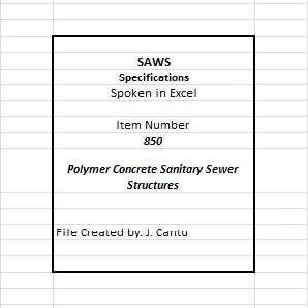7. The test head shall be inflated in accordance with the manufacturer's recommendations. 8. A vacuum of 10 inches of mercury shall be drawn, and the vacuum pump will be turned off. 9. With the valve closed, the level vacuum shall be read after the required test time. 10. If the drop in the level is less than 1 inch of mercury, final vacuum greater than 9 inches of mercury, the structure will have passed the vacuum test. 11. The required test time is 2 minutes.